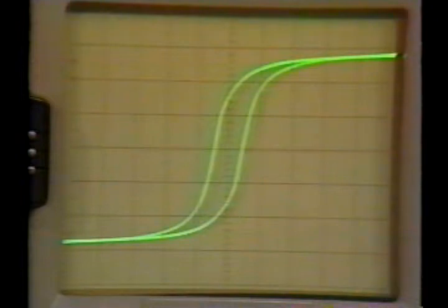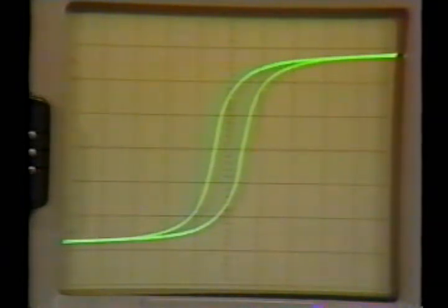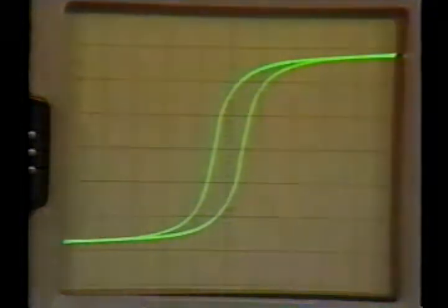The non-uniqueness of voltage in an MQS system can seem paradoxical, yet it is essential to the behavior of a common transformer. When the electric field intensity is essentially irrotational, we can count on its having no circulation around a closed path.